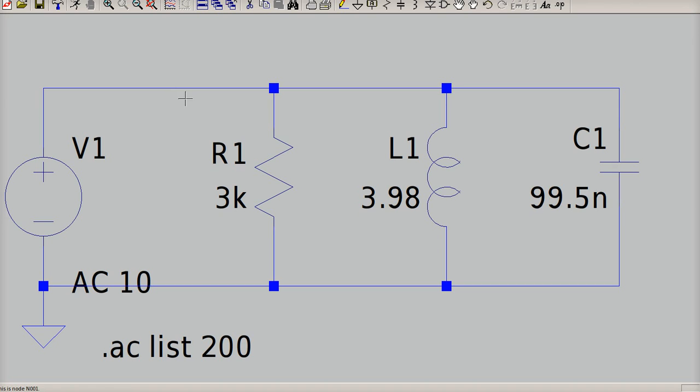The wrinkle in AC is that these currents are not going to be in phase with each other, so they will mix, sort of like we added up the impedances last time when they were in series. You would now add up the currents as complex numbers to get the total current.